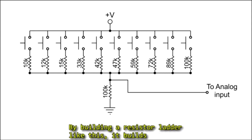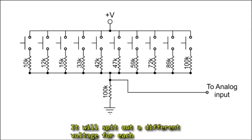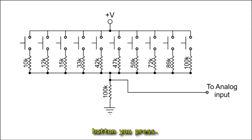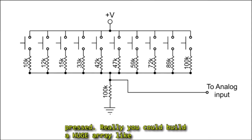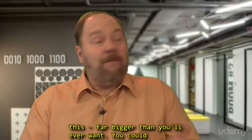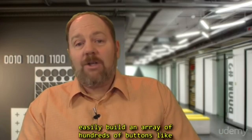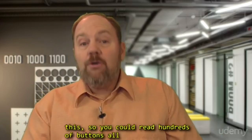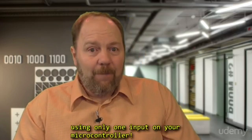By building a resistor ladder like this, it builds a multi-level voltage divider. It will spit out a different voltage for each button you press. Now, you run one line into an analog to digital converter, and that A to D converter will spit out a unique number depending on which button you pressed. So really, you could build a huge array like this, far bigger than you'll ever want. You could easily build an array of hundreds of buttons like this, so you could read hundreds of buttons using only one input on your microcontroller.